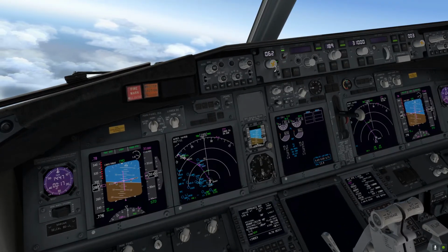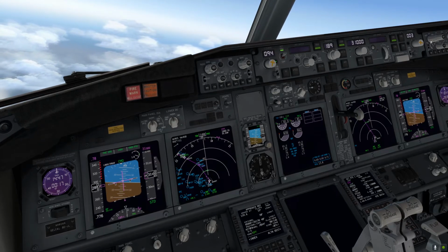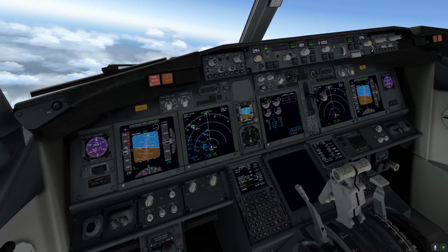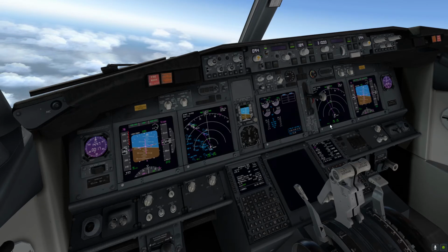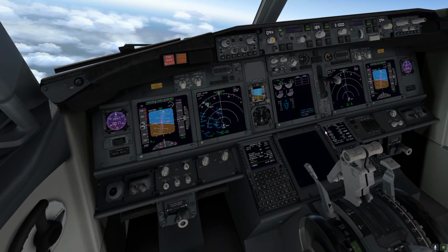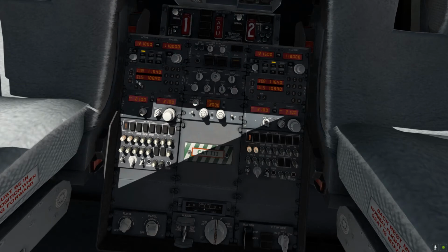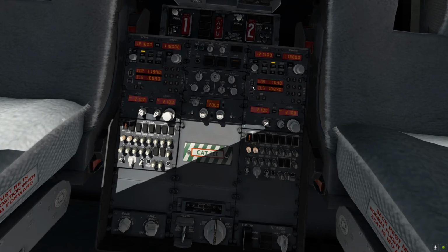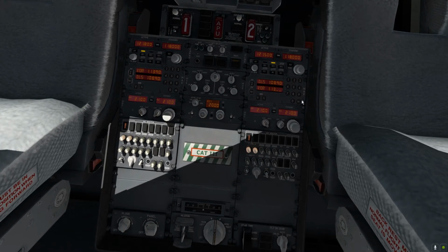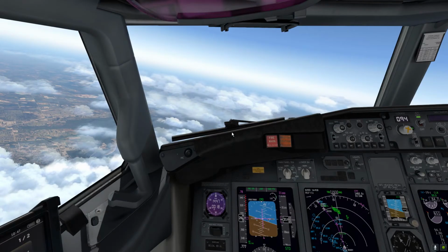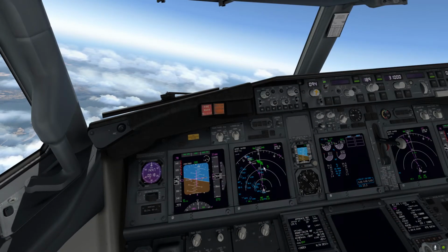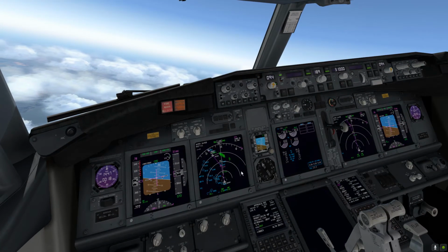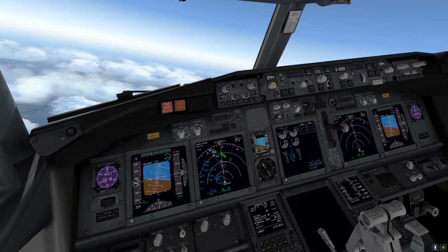094 course, and sorry, 094 here as well. And as a backup, just a Dolphin VOR frequency 113.9 down here, and 113.9 here. Yeah, that's good. Perfect. Yeah, some CBs are showing up about 40 miles ahead, so it will be interesting.